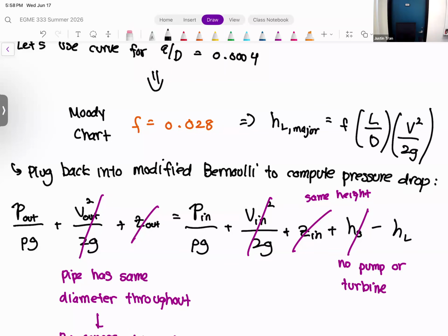Because pressure is just like the average force on the surfaces, correct? Yes. So you do have a net force when you think about it that way. You have higher pressure at the inlet and less pressure at the outlet, and so you have a net force that's pushing it this way. Then that net force is being used to overcome friction. Oh, that makes sense. So if you think about it, in order to move this stapler, I have to put a net force on it to overcome friction, and I have to keep pushing at it, otherwise it's going to stop because of friction. It's the same with fluids. It's just that the thing that's applying that force is the pressure. Thank you.